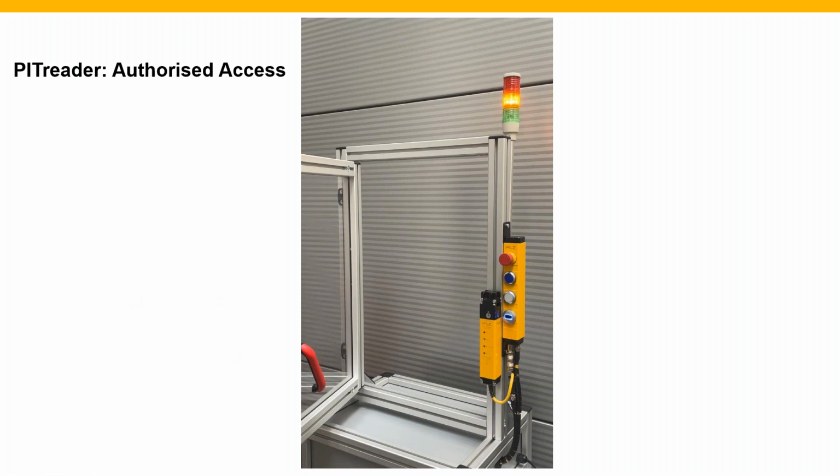It's worth pointing out, if there was more than one operator gaining access to the machine in this case, then we do and will have the functionality of being able to log multiple keys within the area. So once one person has gone in and registered their key, second, third, fourth, fifth, sixth, etc. person can put in their keys and register that they're within the area as well. Only when all 6 or 7 have come out and logged their keys to say that they're out could you then restart the machine.